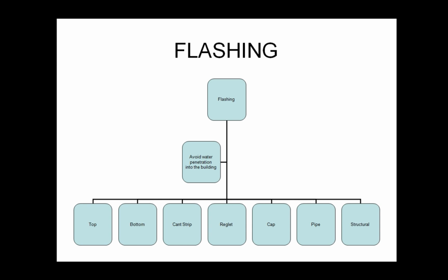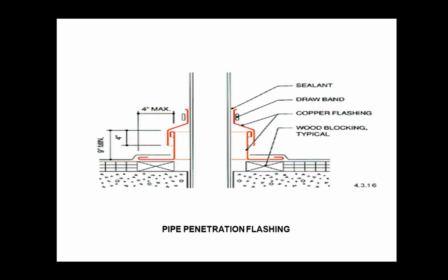All right, so those flashings, as you saw, as you bring up the waterproofing and the roofing material to the sides of the parapets, are there to avoid water penetrating into the building along the sides. So say you have a great roof, but if you don't have the right flashing on the side, that water is going to find its way up and around. So you have to make sure that you have a great connection there, that you're building to your details. And there's a number of ways to do it. We saw a couple of the examples before.